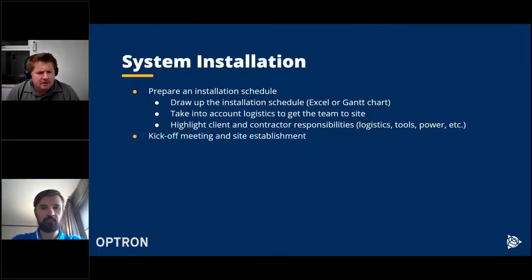When you get to site, best is to have a kickoff meeting and a site establishment. So first of all, we'll have a kickoff meeting, discuss with all the different role players exactly what will happen, and we then go through the installation schedule and highlight items of concern. And then we'll do the site establishment. In other words, we'll actually physically go check that everything is there, all the equipment is there, get everything ready, unpacked out of the crates, so that we can get started with the installation.